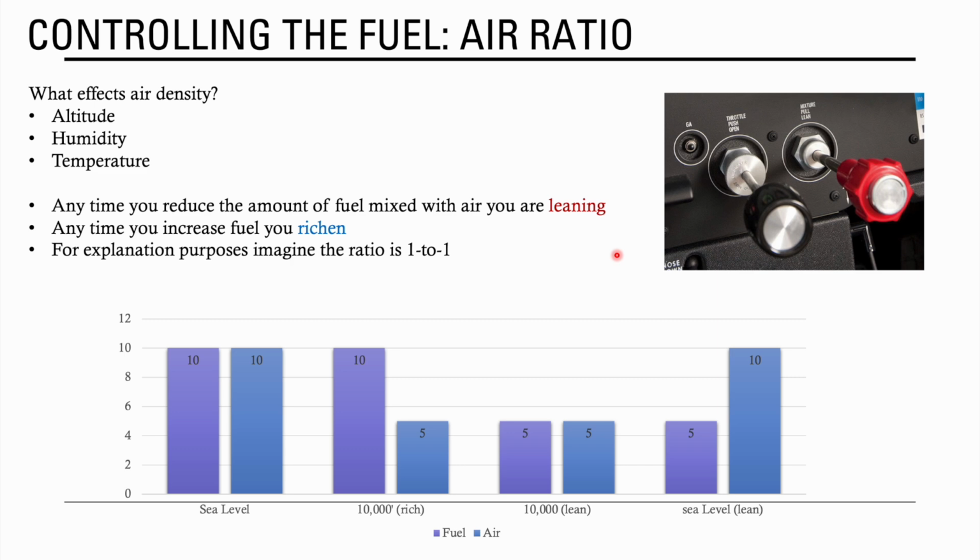I'd say at most flight schools, especially here, a really common problem is people don't lean enough on the ground. And so spark plugs get fouled, and they just have to replace them.